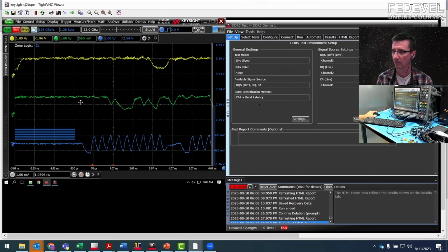So the boundary, the preamble, which is this part right here, and the post-amble, the small part here, is to ensure setup and hold time for the data right here. And we actually have a test for that. We test to make sure this is the right duration. Okay, so this is what people would be looking for when they would be measuring the signals. They would like to recognize when it's read and write and measure it correctly.